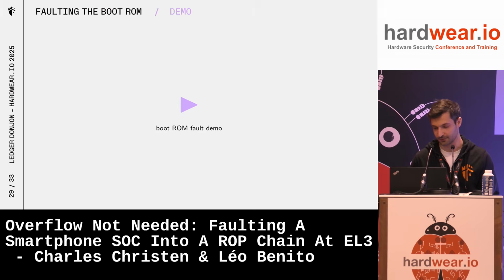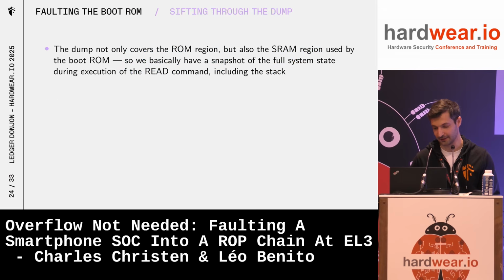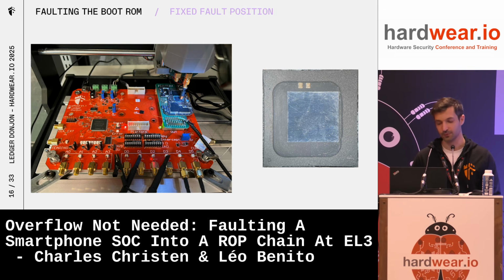So I actually put up the picture maybe. It's a smartphone board. We just took a smartphone that used this chip. We opened it, extracted the main PCB, and then we just soldered onto a Scaffold daughter board which has nothing on it. But then it just lets, maybe you can see the small wires. We can just solder some small wires to test points or pads on the PCB.